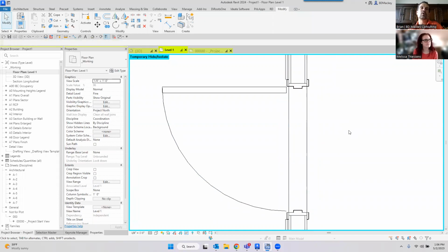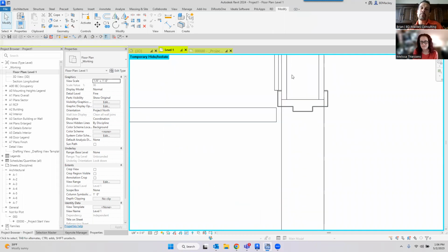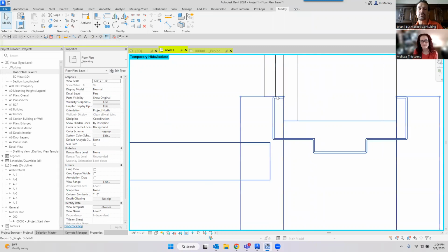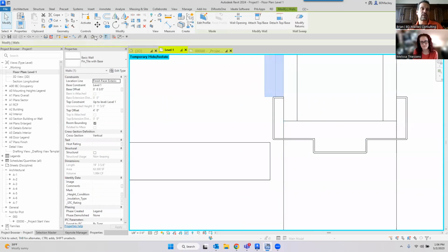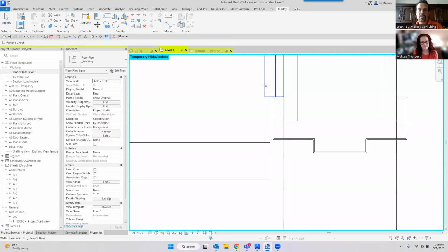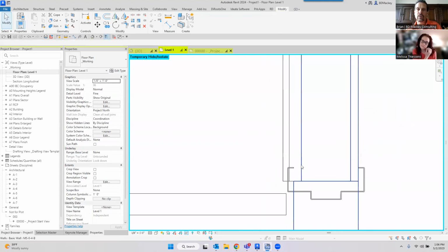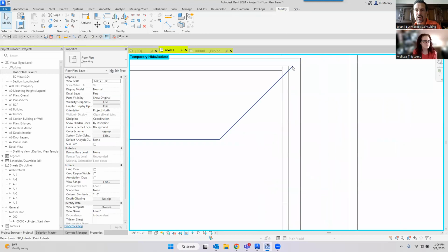That was kind of one of the things I was going into. And Michael said, yeah, but your tile is going to go through the frame. Yeah, but not with the void tool. If I use the join geometry, the tile technically, and again, I can just go through here and do the uncut, uncut this by this, and then I'll do the join this wall to this wall. So yeah, the thin tile would run through, and sometimes you'll even see here, it just lost the line for the gypsum board because I probably have the gypsum board in this family as a finished one, or they're both the same finish or the same level in there.